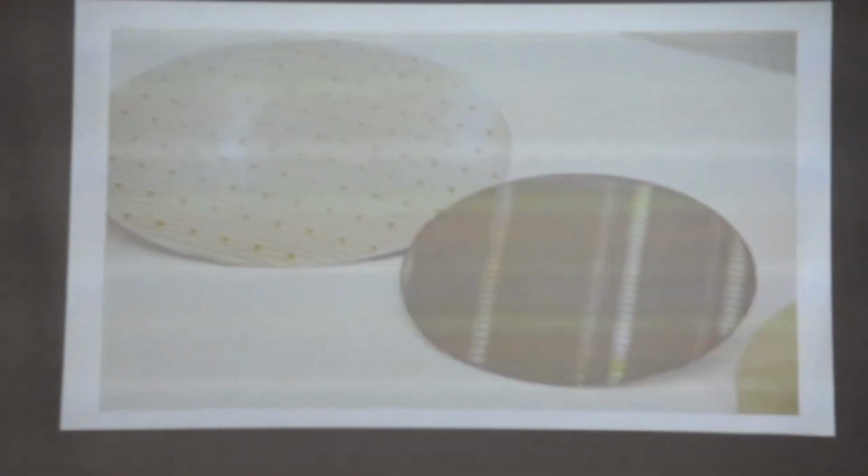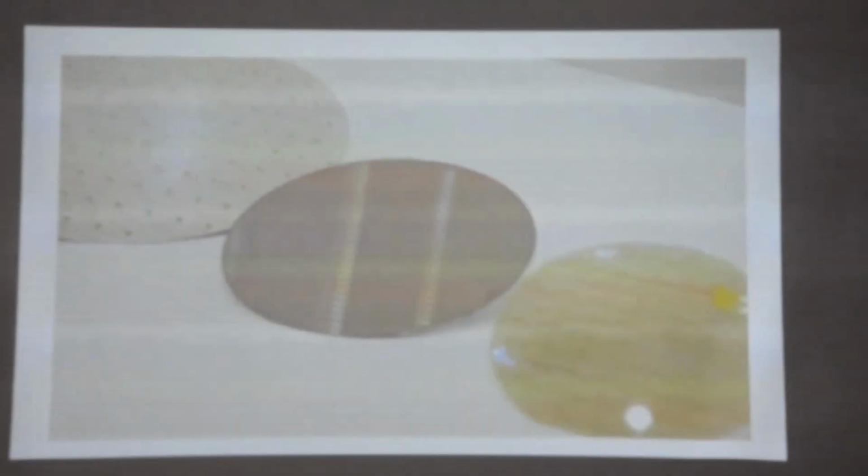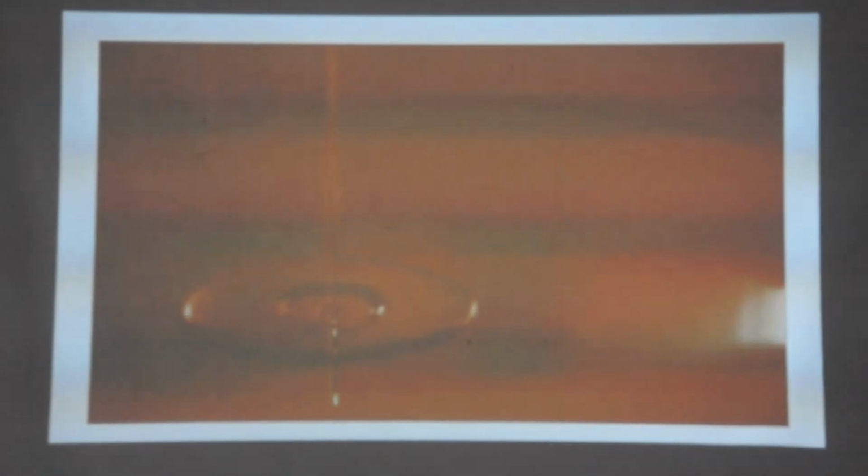In our clean room, up to 35,000 chips are then made from each of these discs. In numerous process stages, the wafers are given their characteristic surface structure. After coating with a photoresist layer, the wafer surface is exposed, developed, and etched. This results in the desired conductor structure.